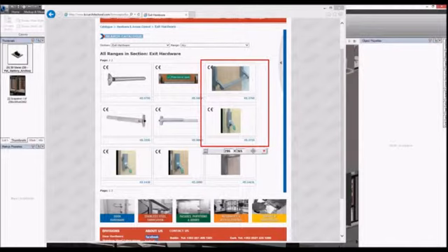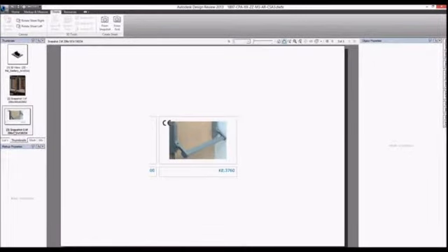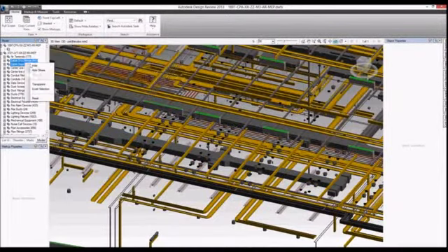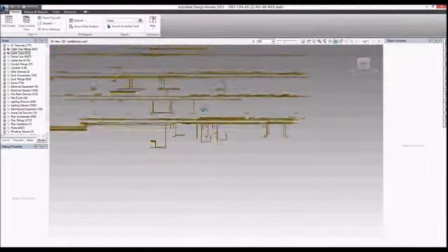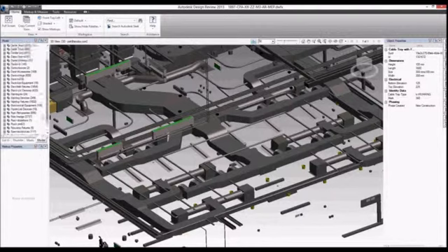The snapshot tool can be used to capture relevant information from other documents also and add them to the Design Review file, and then comments can be added to these using the same markup tools. You can also add other files such as JPEGs, PDFs and CAD files by dragging and dropping them to the Views palette. In the services model, individual services or systems can be isolated, queried and communicated among the project team to give a much clearer understanding of the task required.